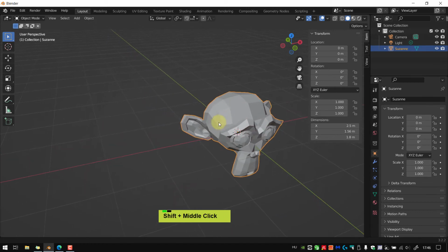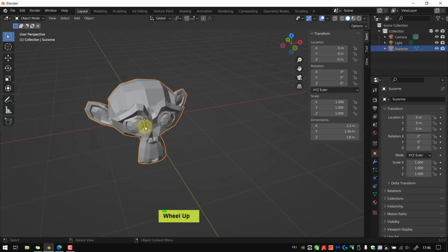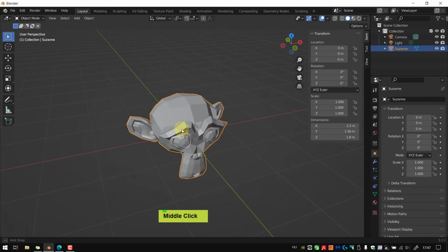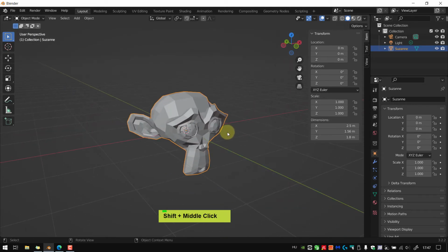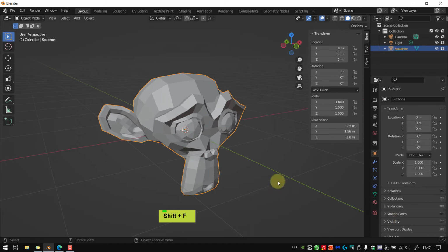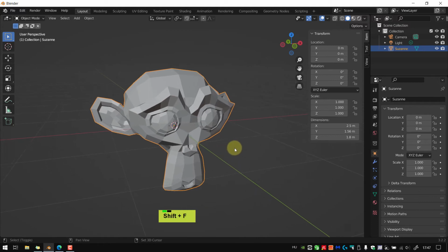Sometimes the virtual camera is just a little bit off. You feel the rotation or moving is not perfectly well. So anytime you can press Shift F, or the original hotkey is the numpad dot. Now I've changed that so it won't work anymore, but Shift F is working for me.